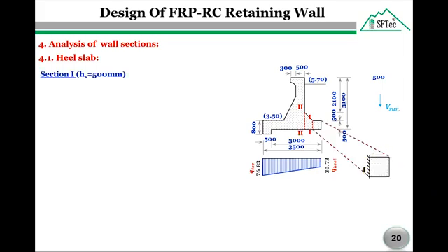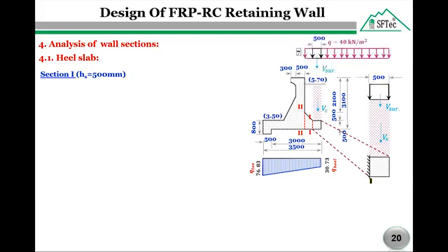For section number 1, the acting loads are the surcharge, the backfill soil, and the own weight of the heel slab at section 1.1.